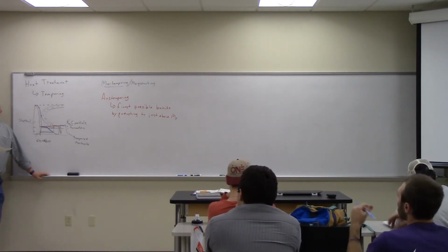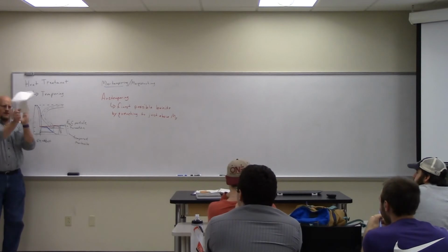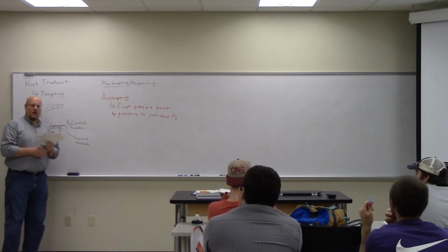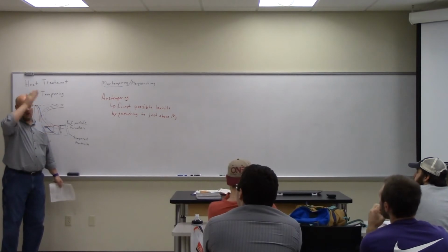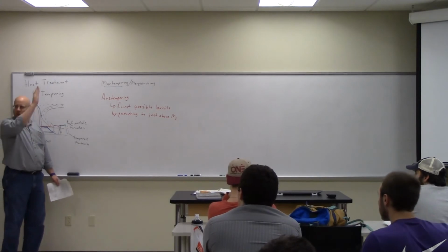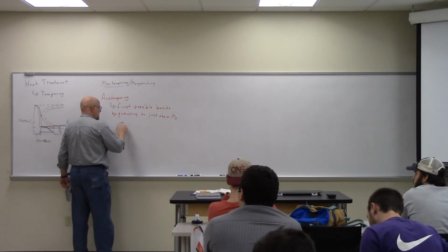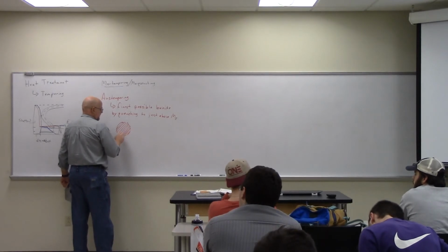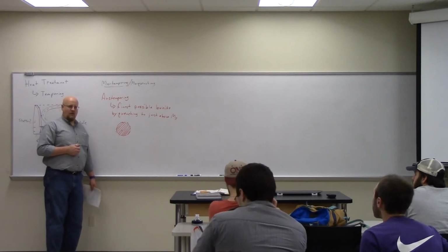Bainite is structured, but it's kind of like, the lines are kind of randomly oriented. Whereas in pearlite, even fine pearlite, the lamella are still straight. So a dislocation can propagate all the way through one of those lines. So pearlite, a grain looks like this. Even if it's fine pearlite, I can get a dislocation to propagate all the way through that chunk of alpha material.